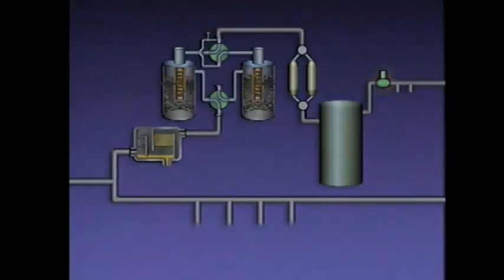throughout the plant. The compressed air coming out of the pressure-reducing valve is distributed by an instrument air header. The instrument air header supplies 50 psi air for use in pneumatic control systems. This pressure can be further reduced by the devices that get compressed air from this header.